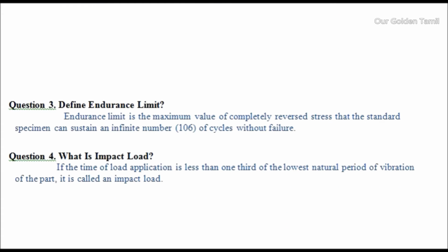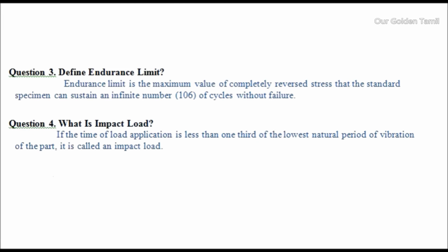Question 3. Define endurance limit. Endurance limit is the maximum value of completely reversed stress that the standard specimen can sustain an infinite number, 10^6, of cycles without failure. Question 4. What is impact load? If the time of load application is less than 1/3 of the lowest natural period of vibration of the part, it is called an impact load.